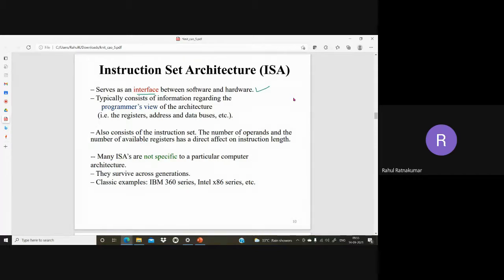That little man has some hardware like a calculator, mailbox, input, output, baskets, and the registers, instruction register, counter, etc. So based on that, we define a few instructions. That is the instruction set architecture, and every processor has an instruction set architecture. So it serves as an interface between the hardware and software. Software code instructions have to be executed on the hardware. ISA is the interface between software and hardware.